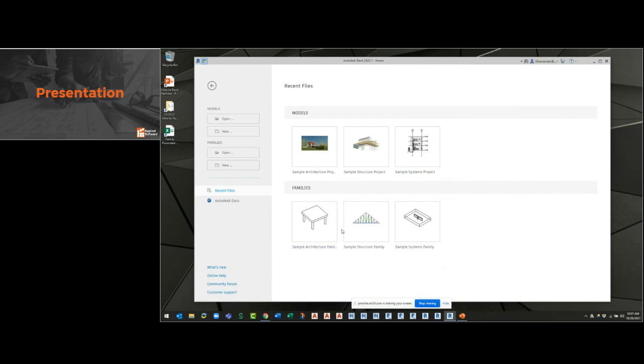We create some really cool custom families, and then next week we get a project, and I want to use those custom families that I spent time on, and that project's in 2020 or 2021. You cannot save any content backwards. So when you load content in a project and you see an upgrade, that's not necessarily an issue unless it's going more than 3 versions back.